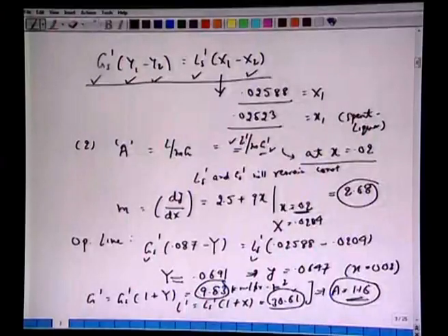LS by GS will remain the same because individually they remain constant along this absorption length, on a solute-free basis. So, in this example the question was to calculate this absorption factor L by mG at the location where the mole fraction in the liquid phase is 0.02.